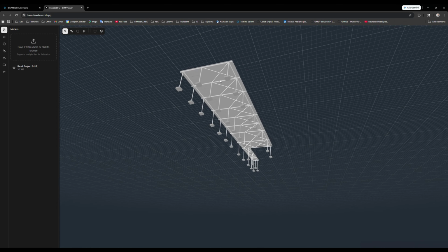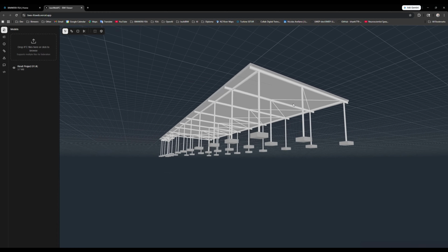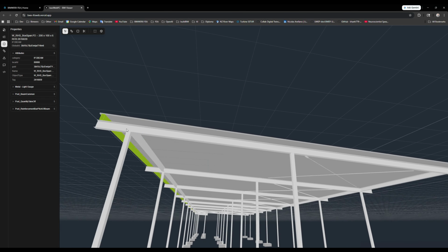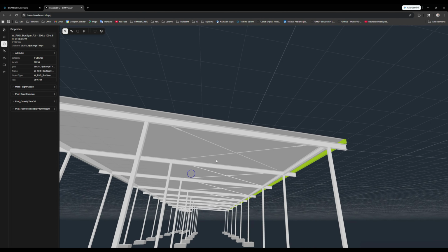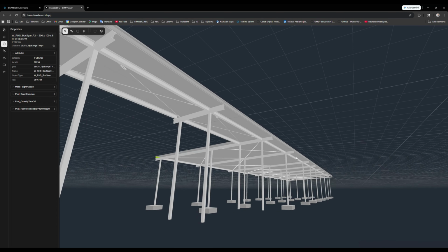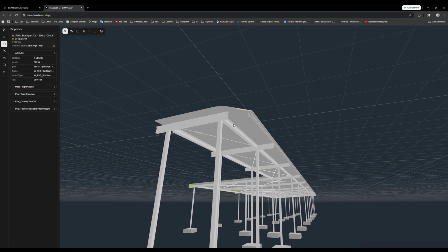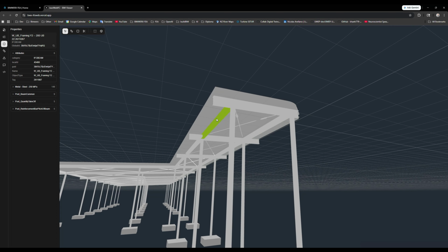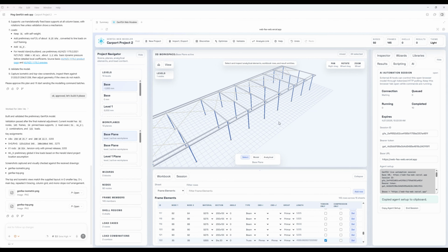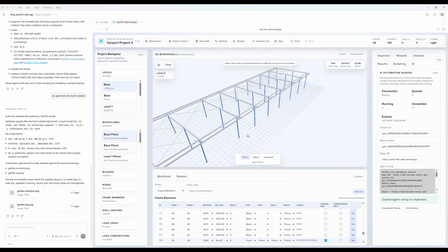And this is the output. So you can see we've had that original IFC model with a bit of an overhang and the purlins at the end there of those rafters that carry the roof sheeting. We've got that cross bracing running across, and then we've got this narrower piece here at the end with the purlin at the one end and just the cantilever there on the other end. And that's exactly what it's modeled. So it's followed the instruction really well.